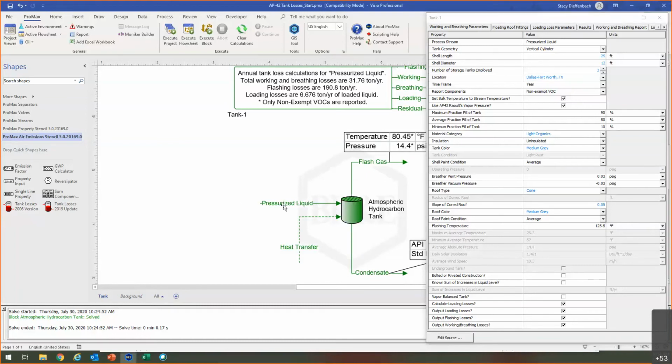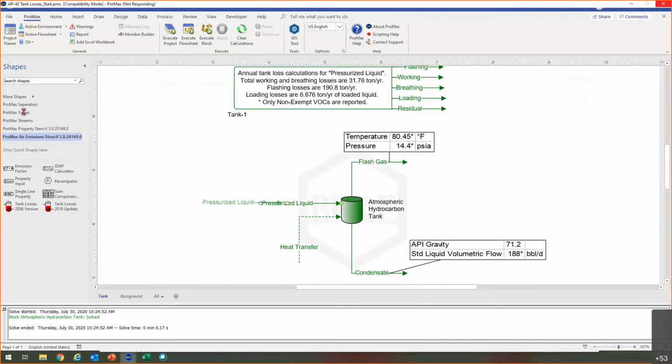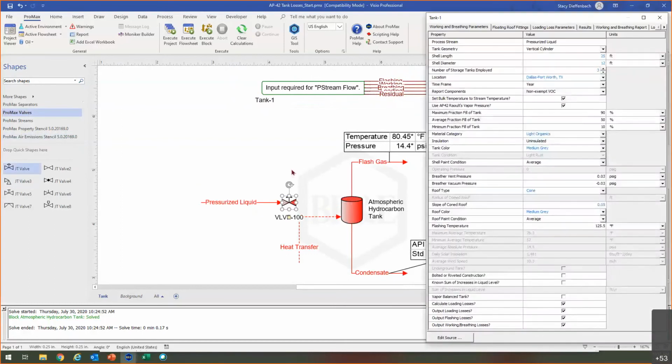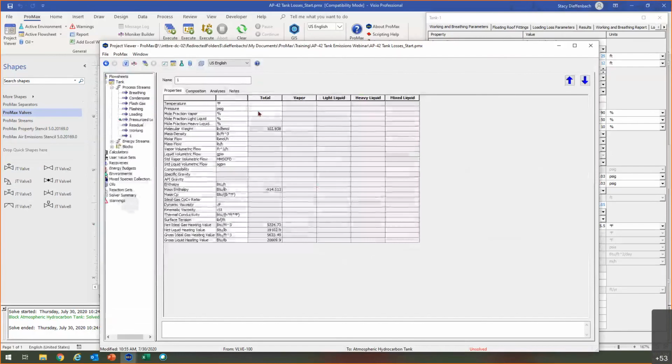So if we do that, and you remember PV equals nRT, as we decrease our pressure, what is temperature going to do? Also decrease, right? PV equals nRT, so it's going to track with our pressure. And so by adding in the valve here, we can tell it to drop pressure first. And I'll set exactly the same 14.4 psi-A.